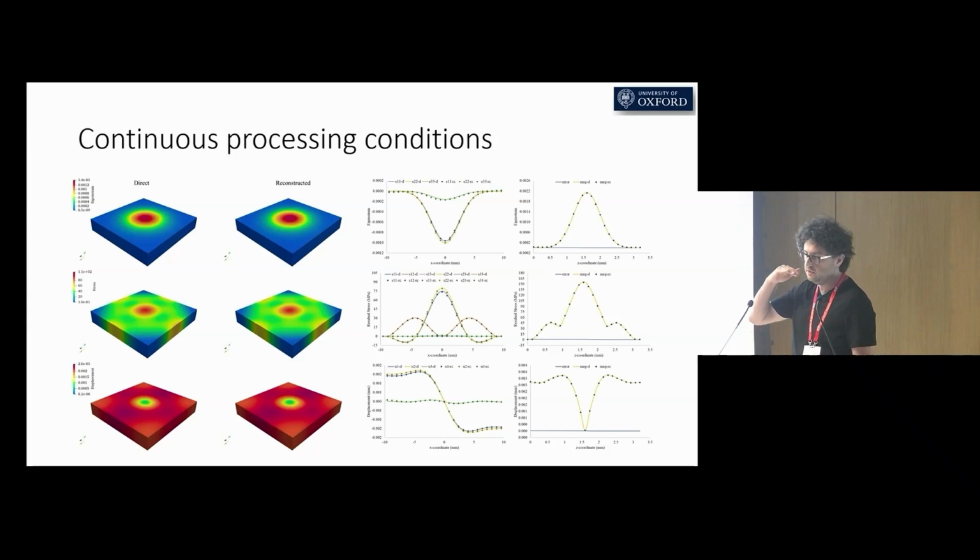We remove this material, which is first connected to a base. We remove it from the base. Displacements after removal of the body from its fixed base are measured and used for the determination of eigenstrains. So in here, experimental data is the displacements obtained from the top surface of the numerical experiment.